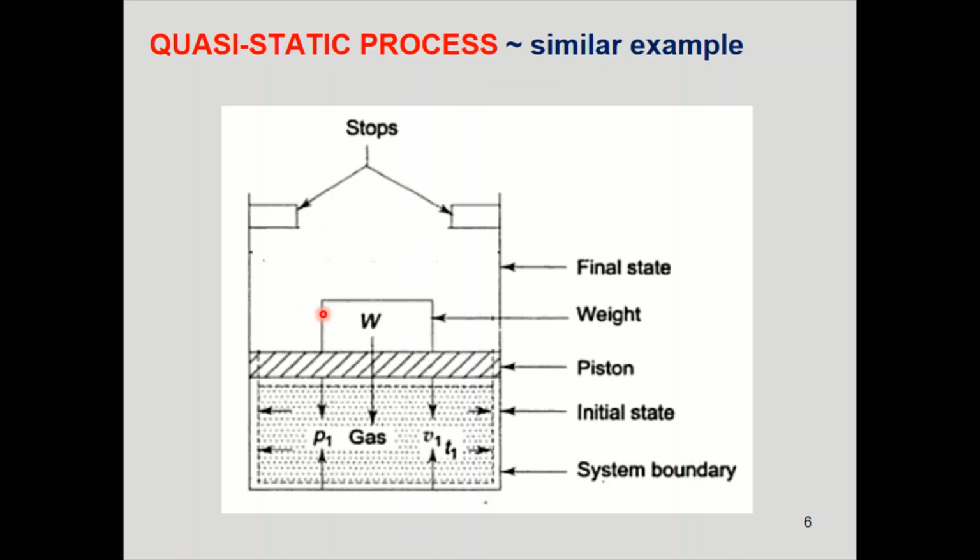But at an intermediate position of the piston, when it was moving up, you cannot have a unique value of pressure, a unique value of temperature, etc. Why? Because it is not in equilibrium. So this process is real. What will be the quasi-static substitute of this?